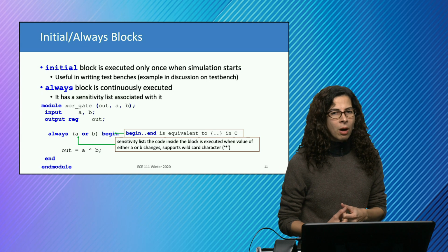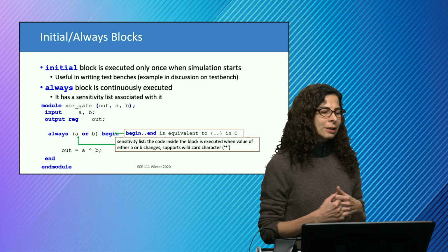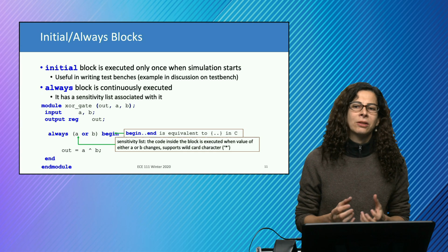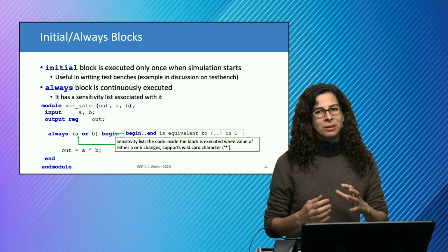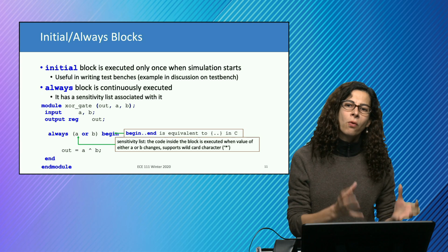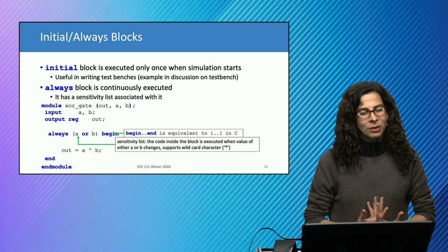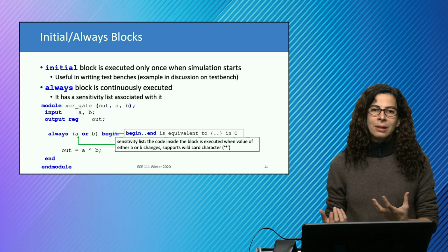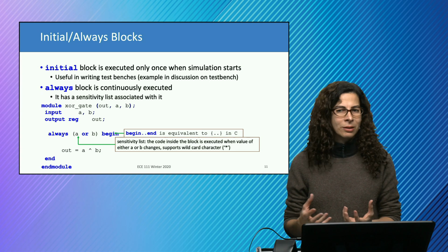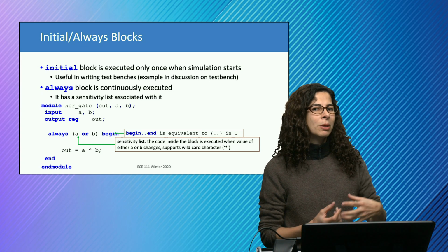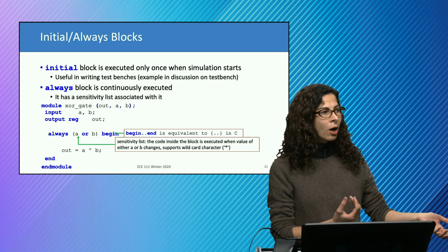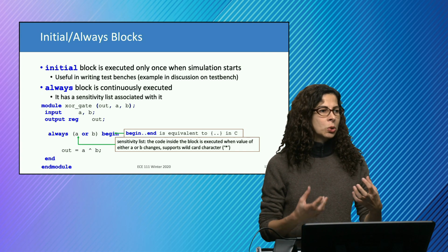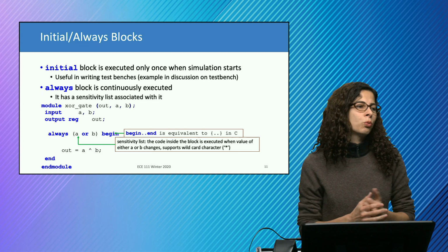The always block is continuously executed as long as its sensitivity list is satisfied, meaning that there is something that needs to occur before the things inside the always block are run. This sensitivity may be, like what you have seen before in sequential design and finite state machines, sensitivity to a clock, or in a program you may assign sensitivity to the inputs coming into one block.